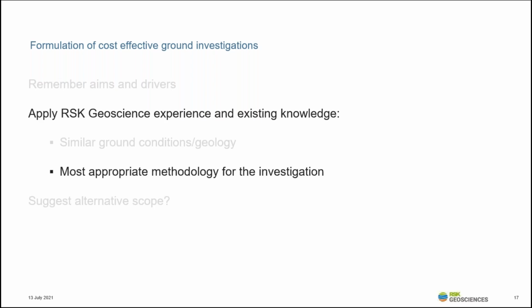If a scope has been provided, based on your knowledge, would an alternative drilling methodology or plant be better suited? Would a track machine be better over a traditional wheeled backhoe type excavator? What about the type of drilling flush? Would air be suitable over a water flush? But considering all of this is not as simple as which is going to provide the quickest results, you need to bring in which is going to provide the highest quality. Are there other things to consider, such as cleanup costs?